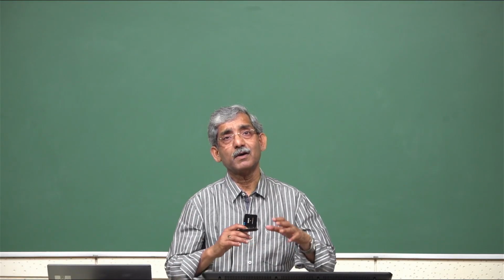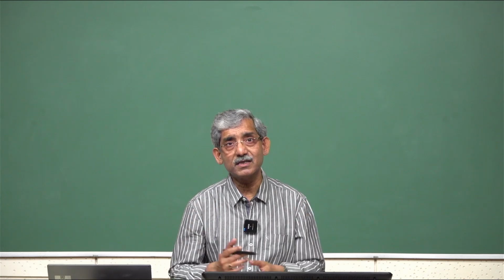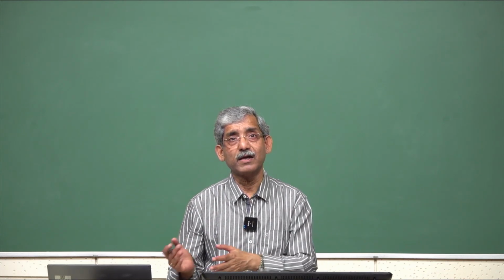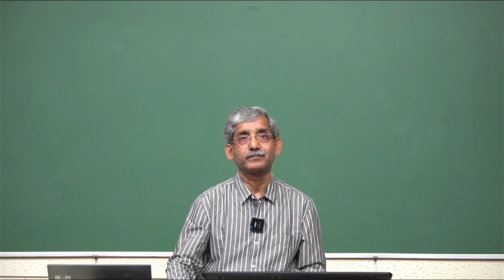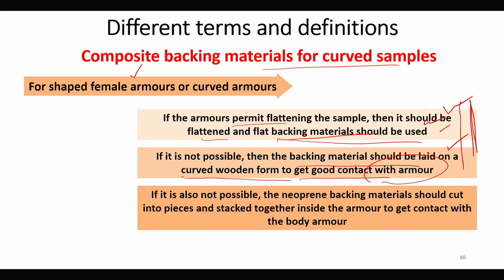If the armor is rigid, then we will try to carve the backing material. And still if it is not possible, then neoprene backing material should be cut into pieces and stacked together inside the armor to get contact with the body armor. So, there are three different approaches.